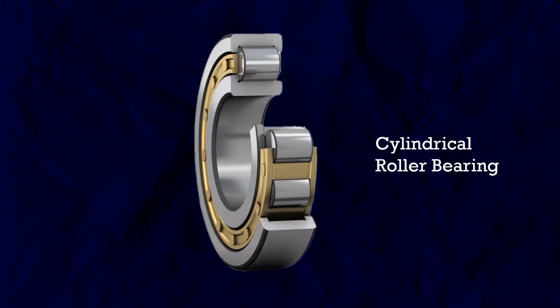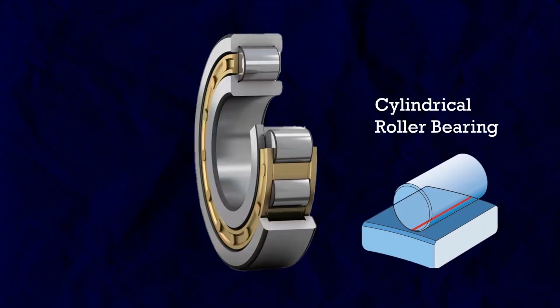And the cylindrical roller bearing can withstand the highest radial load among all types of bearings for the same ID, the same internal diameter, because cylindrical roller bearings provide complete line contact. And whenever you compare two bearings, always choose the same ID. But with a cylindrical roller bearing, we cannot achieve high speed like a ball bearing, because the contact area is high. It's a line contact, meaning high heat generation.